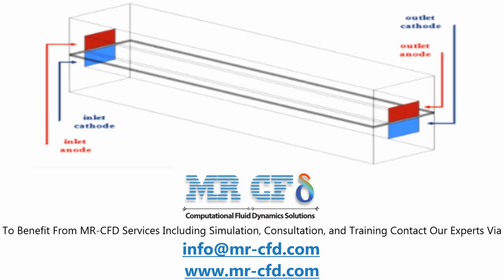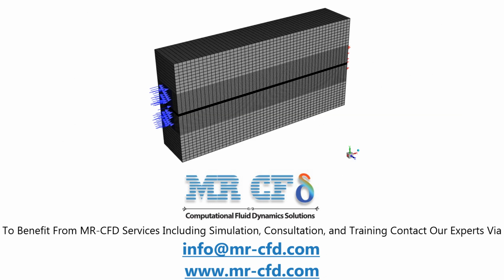The three-dimensional geometry of the present model is designed by Design Modeler software. The present model has a symmetrical structure and consists of 9 regions: 7 specific fluid zones, including cathode and anode flow channel, cathode and anode gaseous region, cathode and anode catalytic domain, and polymeric membrane, as well as 2 solid zones. The solid zone consists of a cathodic and anodic current collector. The mesh of the present model is carried out by ANSYS Meshing software. The mesh is structured and the element number is 142,000.